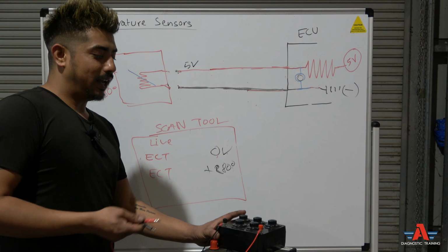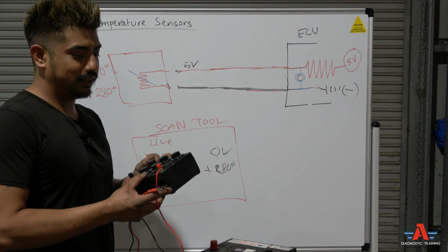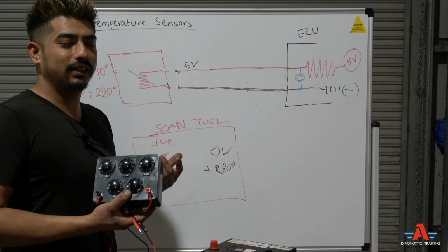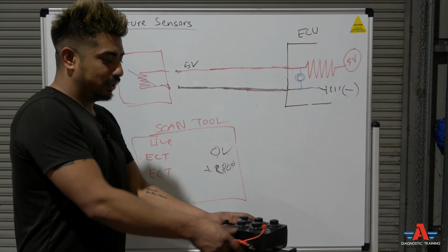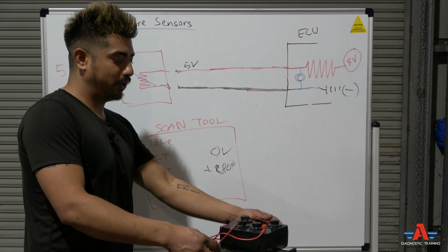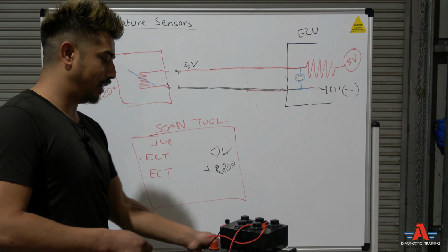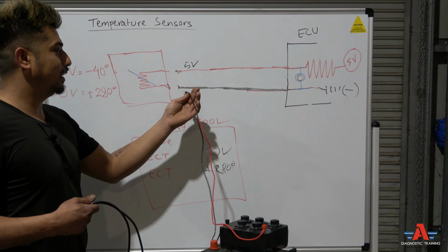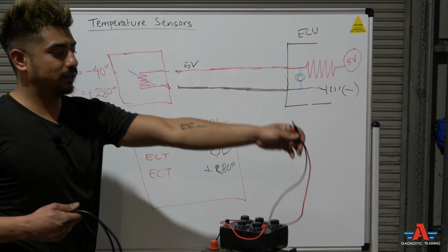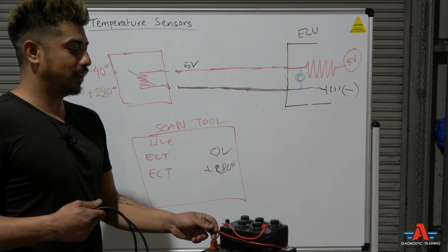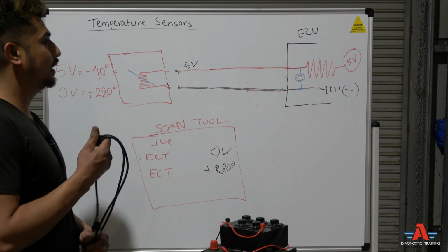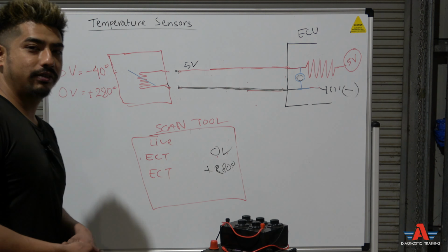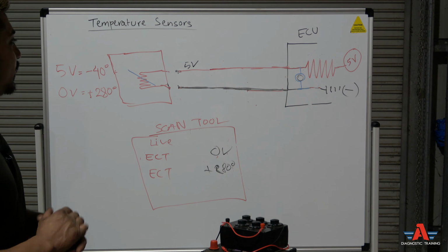But see, if you know all this bypass testing, you can use it to your benefit to sometimes diagnose vehicles like that as well. So that's just a little story I wanted to throw out there, so you know there's other practical uses of a resistor wheel. If you know the bypass test on the coolant temperature sensor circuit, you can do a lot of other things with it as well. Okay, that's just the basics of it. Maybe let's go to the car and do some real practical testing.